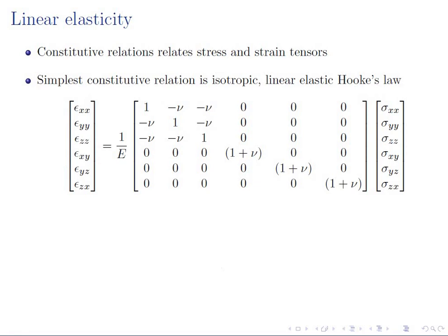We know what stresses are, we know what displacements are, and we also know the relationship between the strains and the displacements. The next thing we need is the constitutive relation, the relation which describes the relationship between the stresses and the strains. For this particular course, we will use Hooke's law, a linear relation. We will assume a linear relationship between the stresses and the strains, and Hooke's law in 3 dimensions looks like this, where this is the compliance matrix.